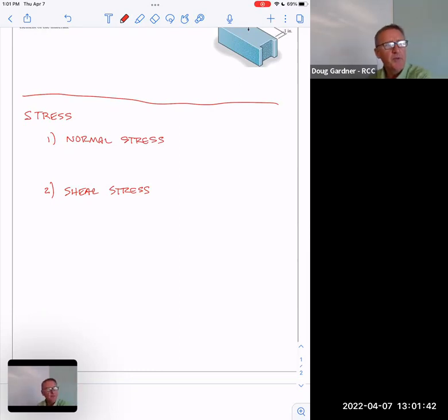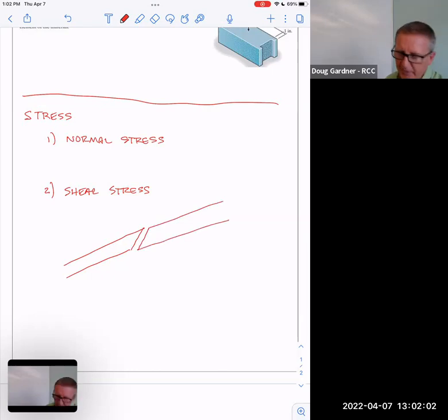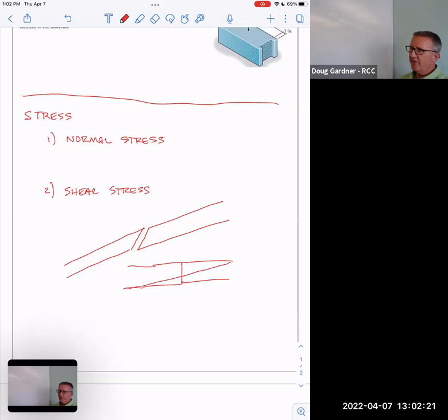Like the first time I ever started building some houses, there were rafters in it that were so long that there wasn't lumber long enough to make them. So I remember the framer, I was kind of surprised by this because I've tried to avoid this forever in my own construction work that I've done. But he basically did this. He took two pieces of wood and spliced them together like that. He put kind of a long cut in them instead of just putting them butt to butt like this. He put this super long, and it was way longer than even what I drew. It was more like this, super sharp and skinny. And I actually kind of understand that now for the first time.